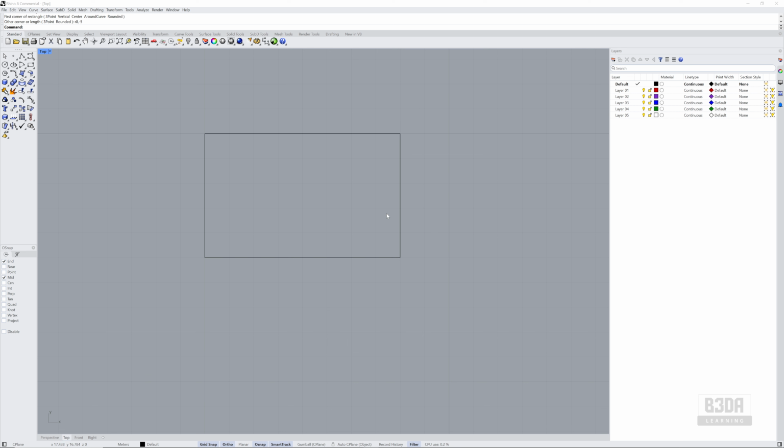In AutoCAD, let's make a direct comparison. We'll usually be working with a command called offset. We have the exact same thing here in Rhino, but for curves. Let's go to Curve Tools, and here's the offset option. I will left click. You can see that we have an offset curve and offset multiple. Right click here, left click, and you can change the distance by using the command line here. Let me change the distance to 0.15 to create just the thickness for the walls.